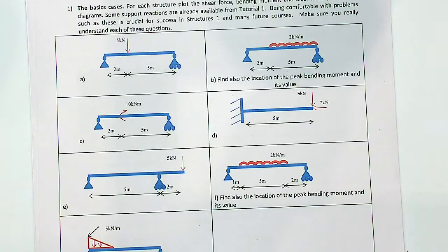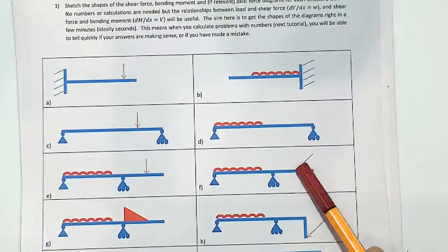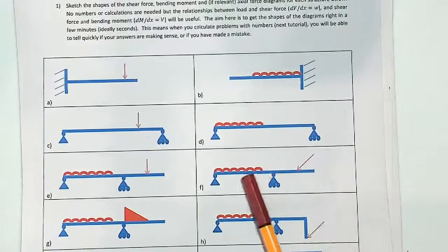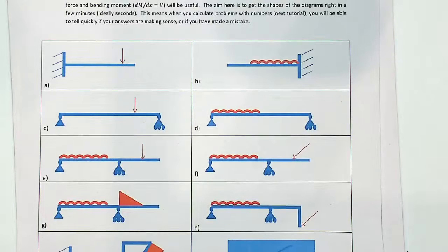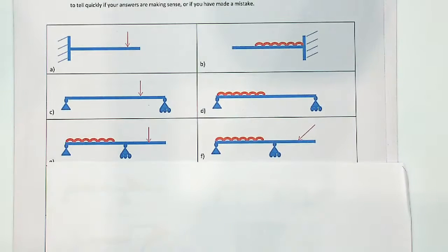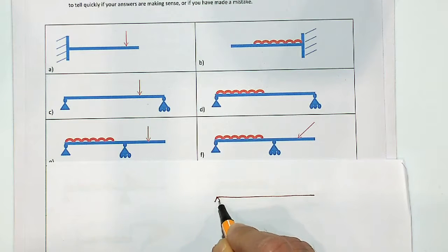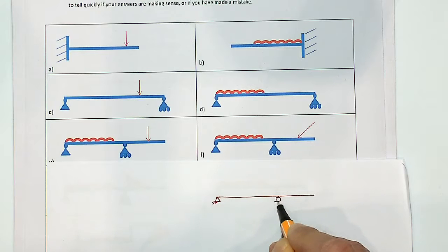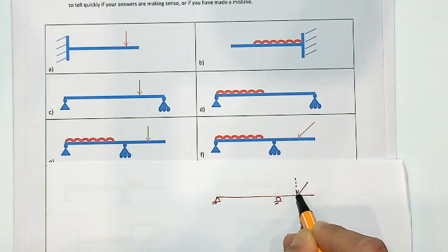Okay, the axial force diagram, yeah. Some problems have a horizontal component of the load, for example here, so there is a possibility of having an axial force diagram. For that problem, you have the load here, and then this is the roller, and you have a load here. Now this load you can divide into two parts: one vertical load and one horizontal load.